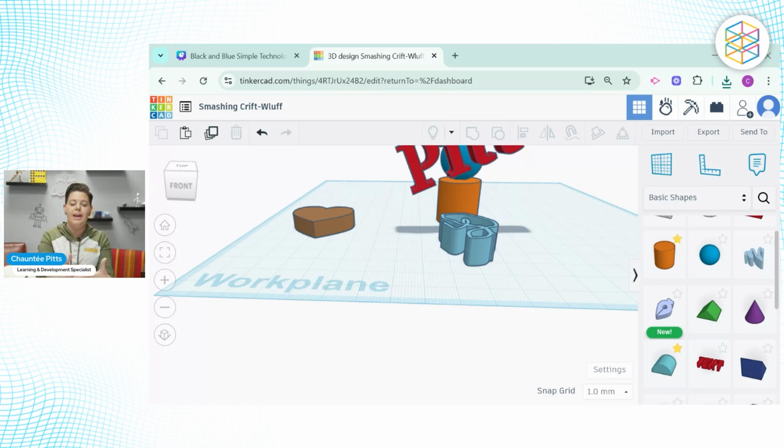I put that image onto the cloud print, and then I transfer it into a G code. G code is the thing that you need to have for your printer. A G code is a non-editable file that is already created into a layer, and that is what is used on the printers. It's really frustrating at first because you're like, STL should be for everything. I don't disagree.